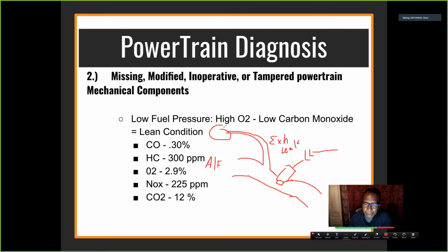Then there's a valve on the system that directs the air behind it to the catalytic converter. This right here is supposed to go to the cat. But if the switching valve goes bad, or the command goes bad and it stays upstream, I'm going to have that same amount of air in front of the O2 when it goes into closed loop.